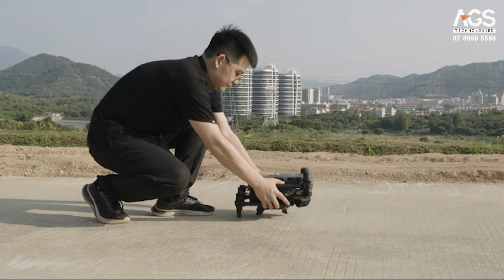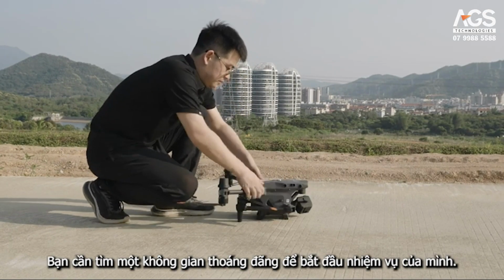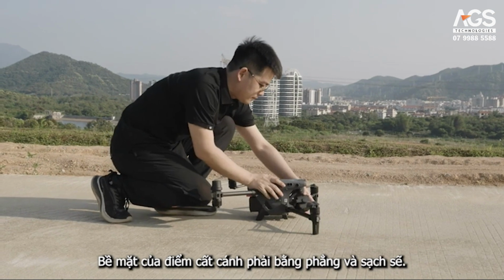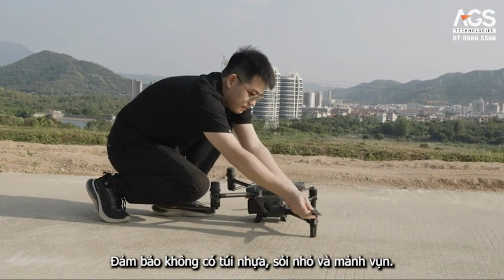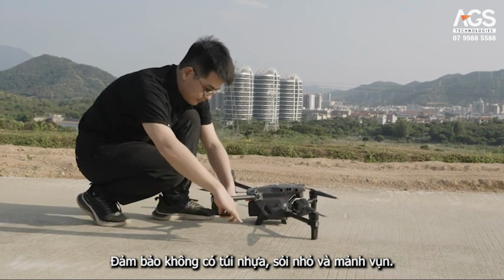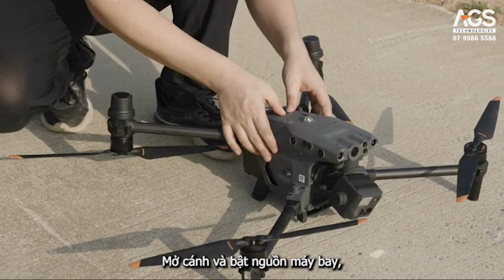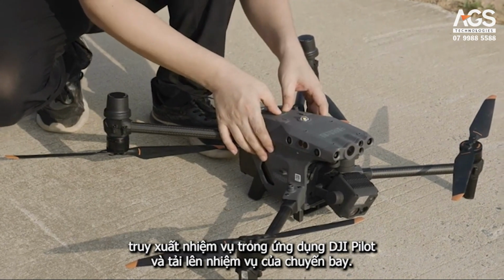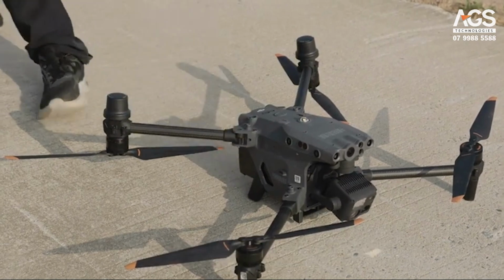Pre-flight check. You need to find an open space to start your flight mission. The ground of the takeoff point should be flat and clean. Make sure there are no small pebbles, plastic bags, and other debris. Expand and power on the aircraft. Retrieve the task in the DJI Pilot app and click Upload Flight Mission.